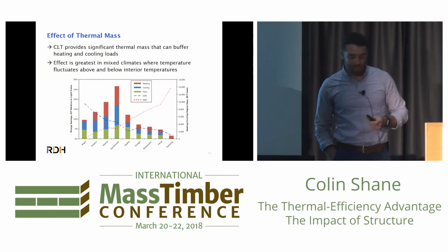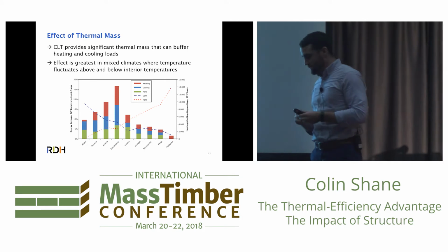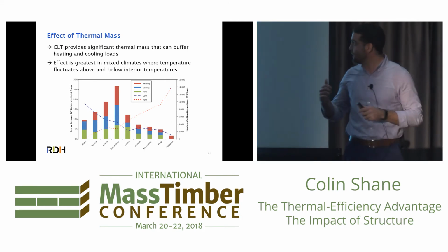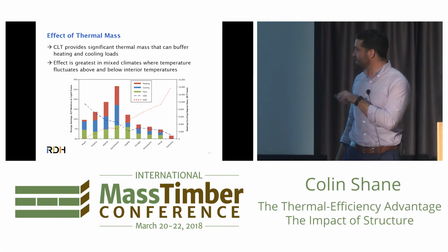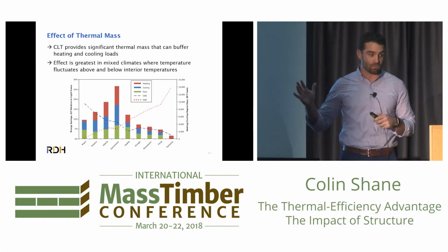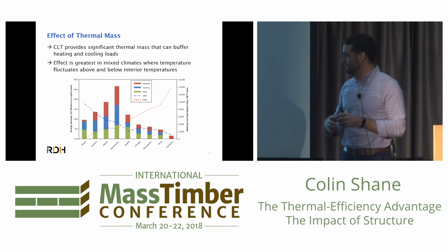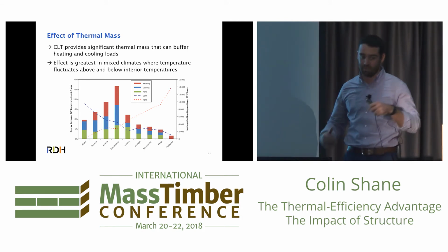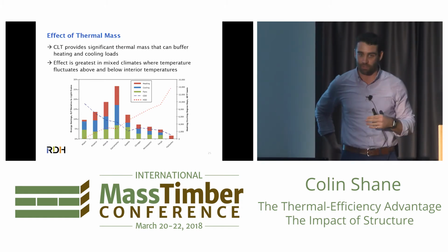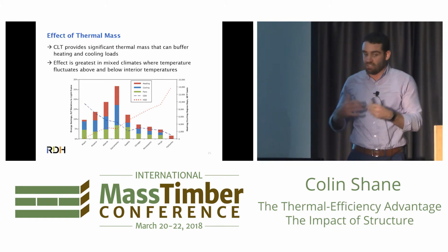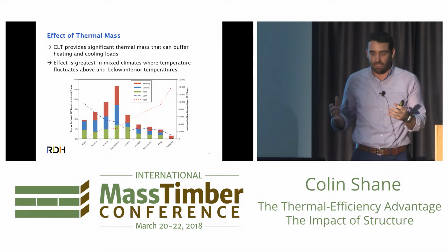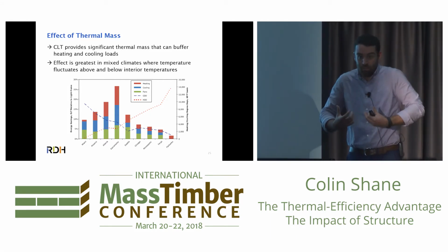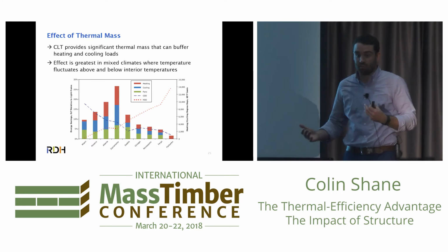One of the major last effects that we do see with CLT buildings, mass timber buildings in particular, is the effect of thermal mass. So this is a graph right out of the CLT handbook for those who are familiar with it. There's a building enclosure section of the CLT handbook that we authored, and this graphic is right out of there with a whole bunch more description in the background if you're interested. But there is thermal mass to CLT. CLT can absorb heat and store it for a while. It can bulk up and basically store heat and then release it slowly over time.